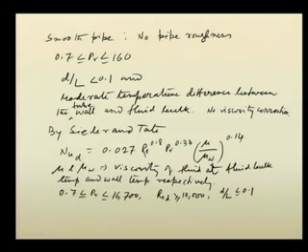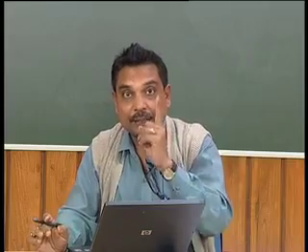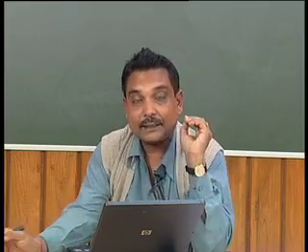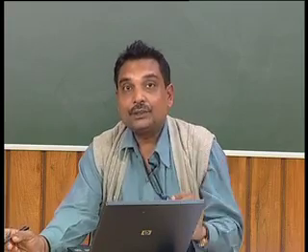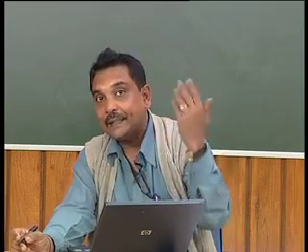So this is the Sieder-Tate equation, and in both cases, a very important thing is that some physical properties are involved in the dimensionless groups. These physical properties are rho, mu, k, Cp.